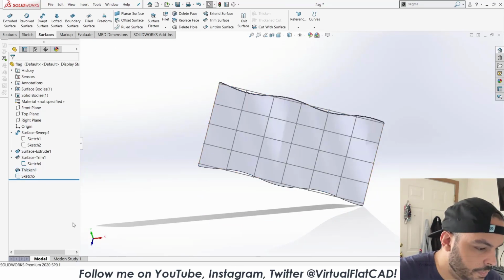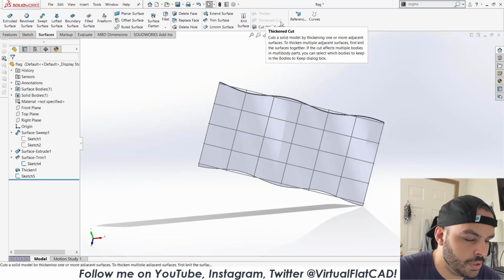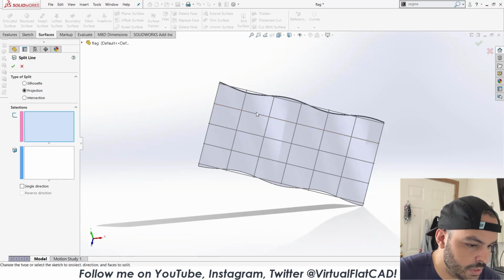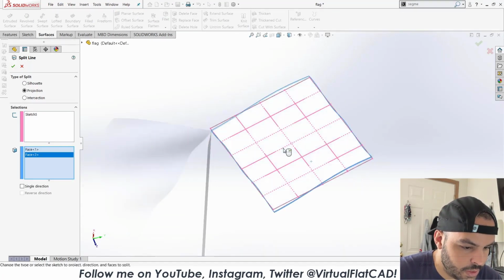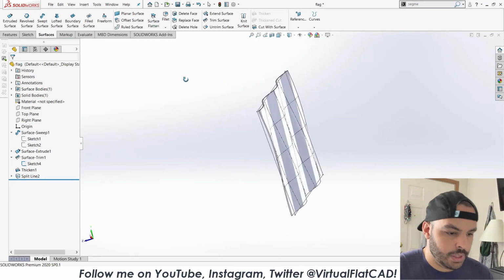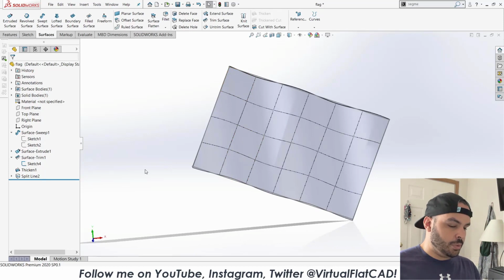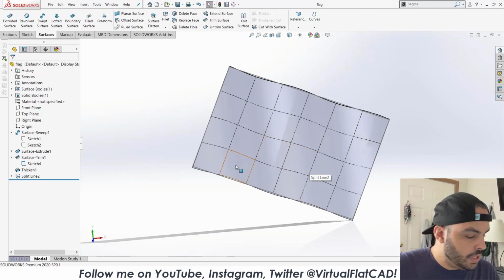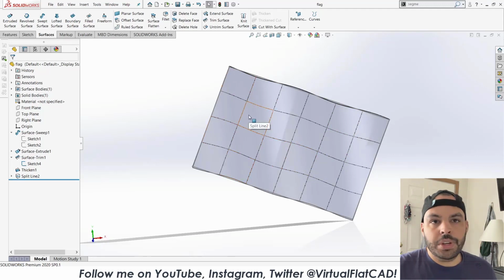Do that. And then let's just say split line again. Curve split line selections is this. Yep, and that seems to have worked. Our flag both has actual thickness, and we have it subdivided. So that's pretty cool. Although I guess you could keep it as a surface since we're just doing an animation,